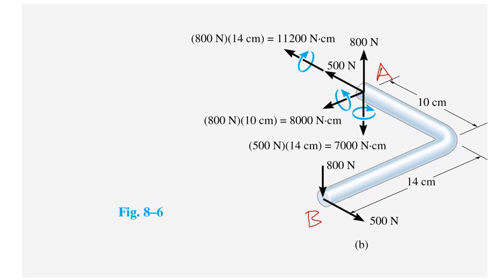No, forget about that. So we have 800 newtons times 14 centimeters, which will give you a moment about the y-axis, and that becomes torsion, right? If you look from the y-axis, this is y at the end here, this is counterclockwise, right? Therefore, at the cross section here, you have a clockwise reaction of 800 newtons times 14 centimeters. Okay, so that's the moment about the y-axis.